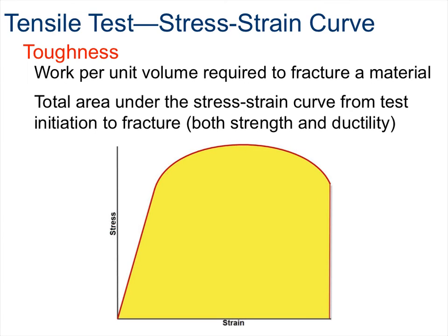Toughness refers to a material's ability to absorb energy that results in permanent deformation. This material property can be thought of as a combination of both strength and ductility. For instance, the head of a hammer must be made from a tough material, or it would shatter on impact with another hard material. Though it does not provide the accuracy of an impact test, the total area under a material's engineering stress strain curve will give the engineer an indication of how a material will perform under impact conditions.